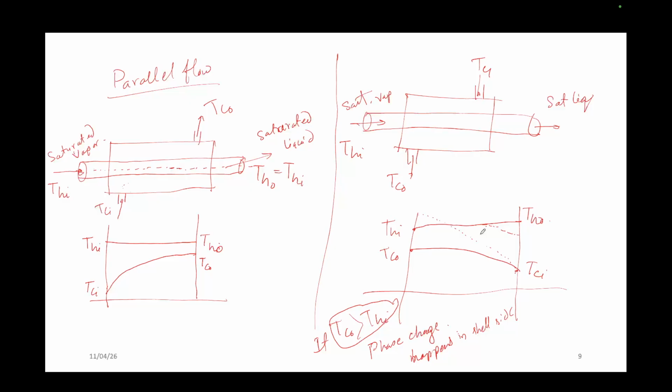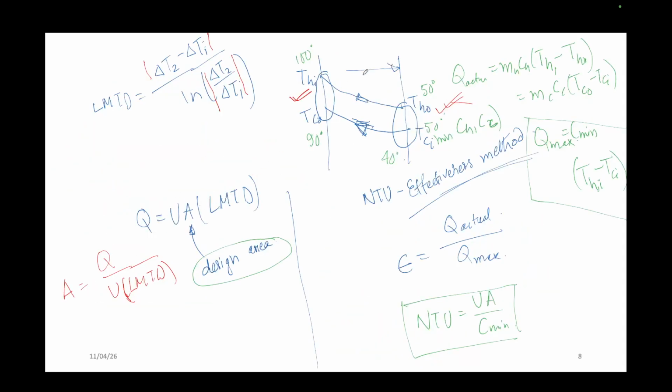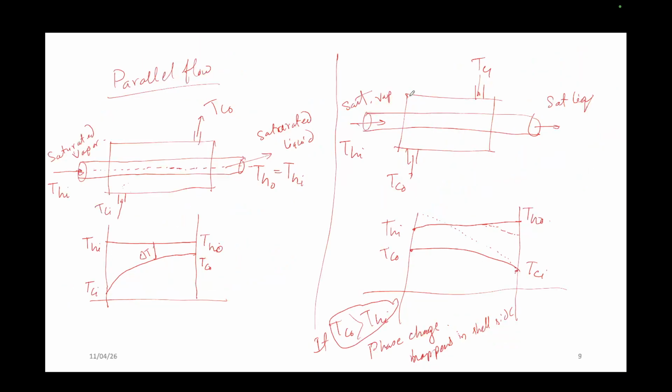So if I talk about this counter flow or whatever flow, basically this ΔT1, this difference, if you take the difference anywhere, that is your ΔT. So for LMTD, you get what ΔT is. This one is your ΔT. ΔT1 you can take on the left side or on the right side. Please remember this because that will help you to solve numericals.